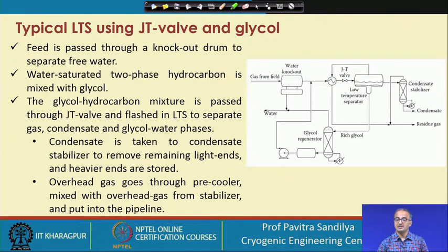So, one phase is the lighter gas here, which is going to be our product, and this is the water rich phase which is taken from here, and this is the glycol rich phase which is coming from here. So, this glycol rich phase is taken over here into a regenerator system. The water which is coming out from the glycol rich phase is again taken out from the system, and the glycol which is coming here is taken through this pump and is fed back to the system.